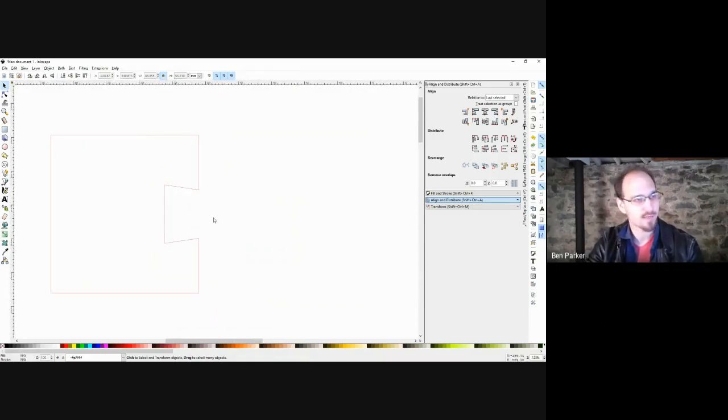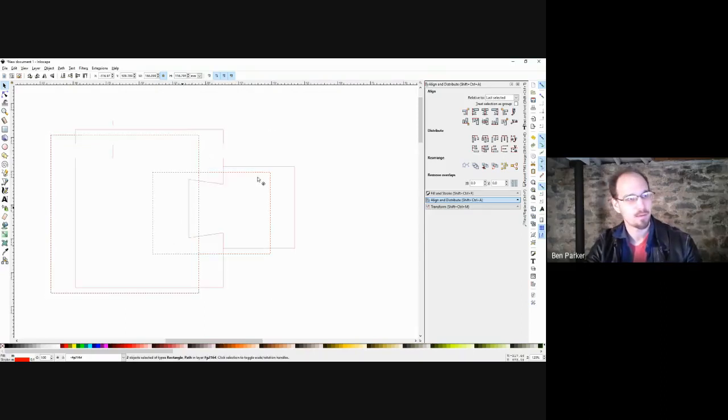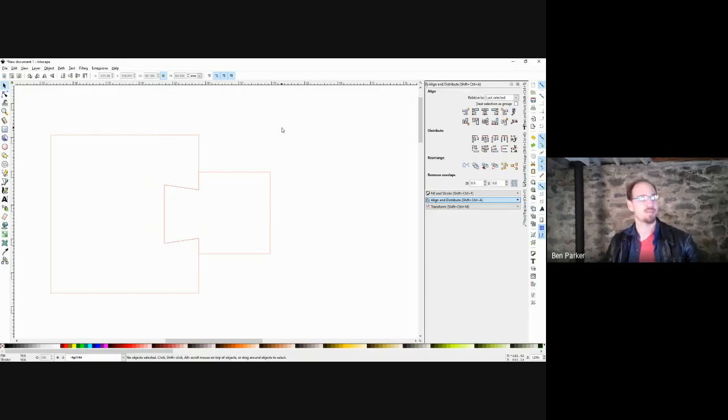The process that I did for getting the exact shape here is I drew a rectangle. I know that there's the hole under here that I need. I'm going to click this and duplicate it. So Control D. Select these two. So right now I've got two different shapes, but I'm keeping my original. So I select that one, and I do a difference function. And now I've got that puzzle cookie cut shape.